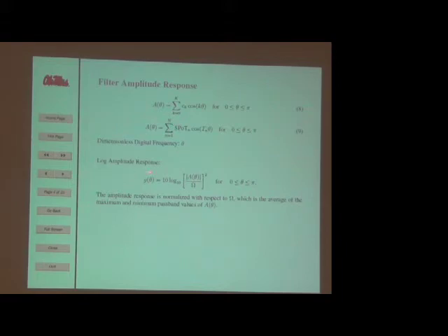And I actually want to, my specification is typically given in dB, so my model is actually the log of the amplitude response. I don't care about the passband gain of a digital filter. I can adjust for that later. So this is normalized by the passband gain. So this is actually, if you will, if this was a model selection problem, this would be the model.